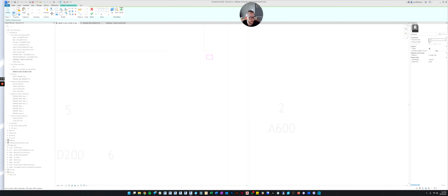So if you look over here at the settings, you can see the extrusion starts at 0 inches off of the main level, because the work plane it's associated to is the main level. So that's good, but it's only going up 4 inches. We actually want it to go up all 9 feet from the floor to the ceiling. So let's put in 9 feet.